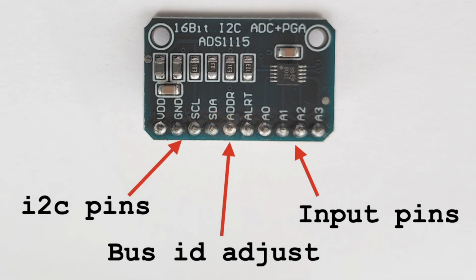We're going to be using a module based on the ADS1115 chip. This provides 4 analog inputs and these can be read on the I2C bus. The connections on the board are really easy to see, with the inputs at one end and the I2C connections at the other. In the middle there's an extra pin which you can use for changing the address.